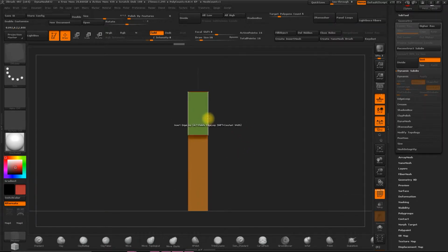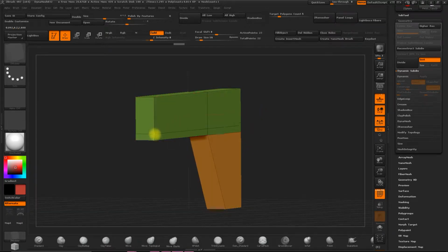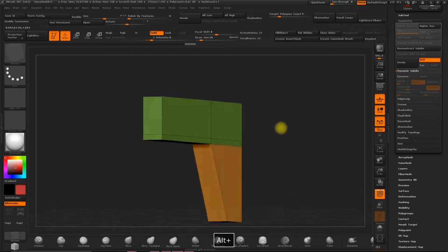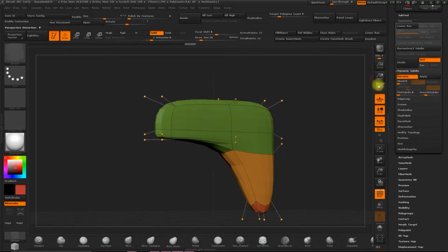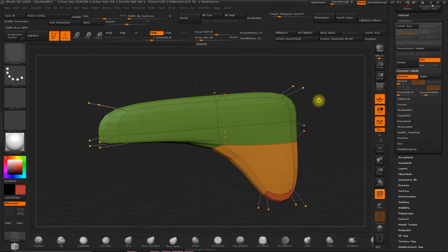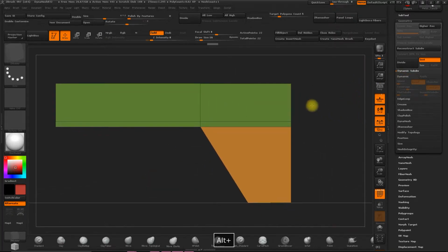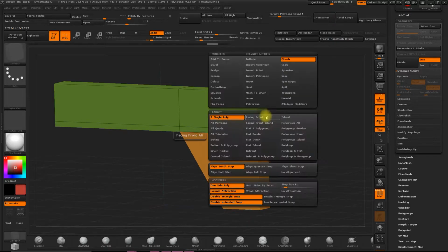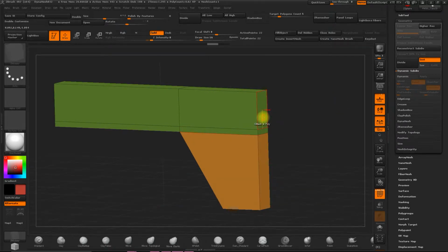Okay, now we can add in a cut here, around here, to indicate that we want a kind of curve, but not too pronounced, like this, more or less. If we go to dynamics, we can see how the model is turning out. Look at how it's still a little bit too organic. We're missing some cuts. Now we can make a selection and simply make an extrusion to just the polygon. Remember to click on single poly, and we're only doing it on one polygon.